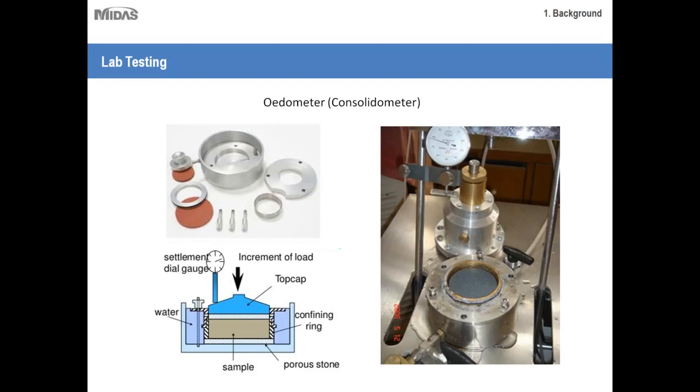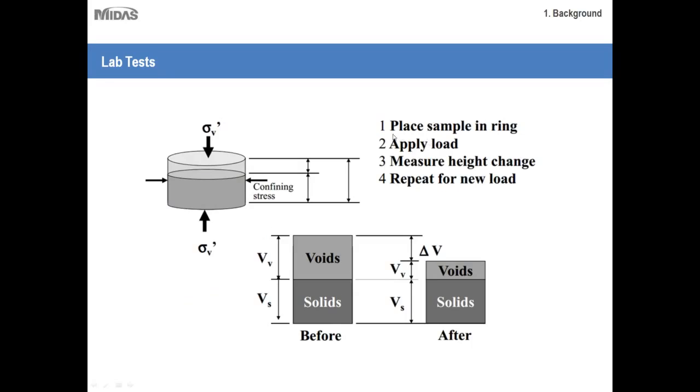Then a rigid loading cap is placed on top of the upper porous stone. Once that cap is in place, you'll load it. You'll connect it to this steel rod, which simulates the load increments, and it's all rigged up to this loading frame. This is essentially what you'll be studying: how over time that specimen will settle as that load is constantly being applied to it.